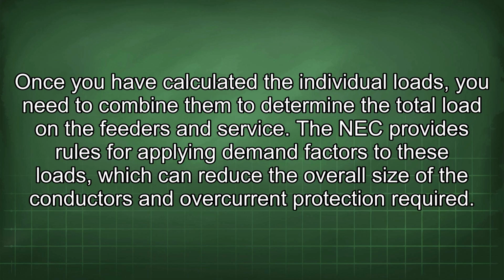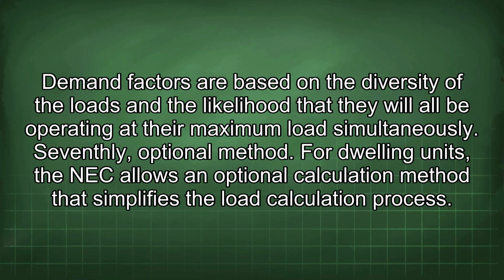Sixthly, feeder and service calculations. Once you have calculated the individual loads, you need to combine them to determine the total load on the feeders and service. The NEC provides rules for applying demand factors to these loads, which can reduce the overall size of the conductors and overcurrent protection required. Demand factors are based on the diversity of the loads and the likelihood that they will all be operating at the maximum load simultaneously.